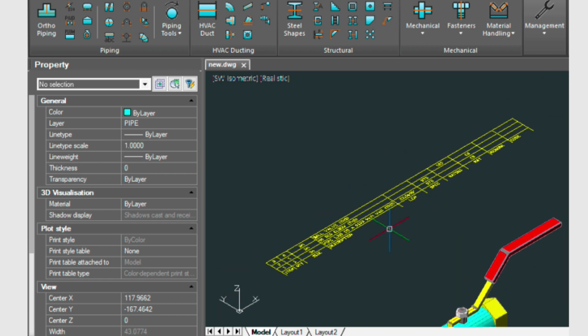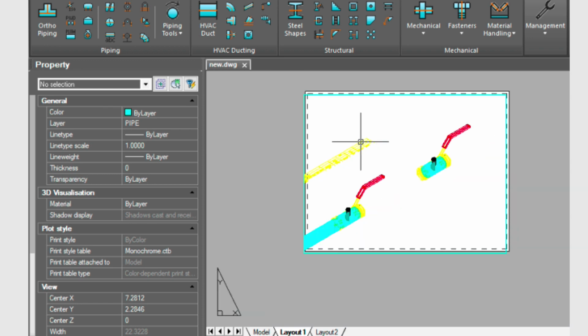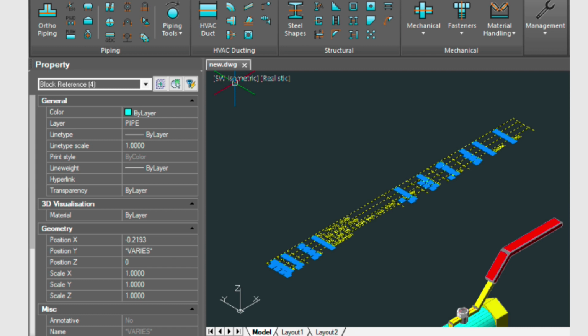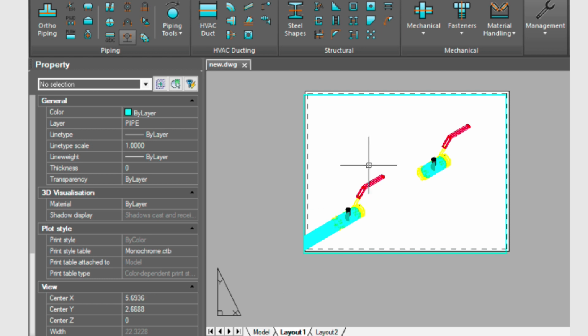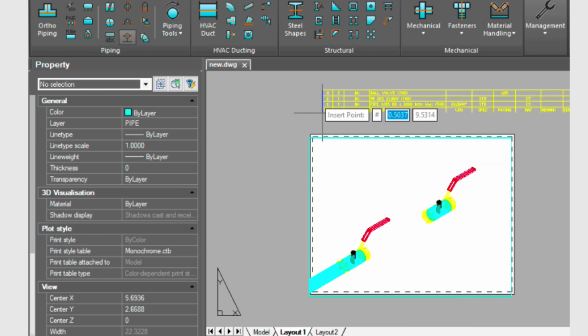Now, to get this schedule into paper, cutting this and then pasting it into paper space. If you want to hang in there, I'll show you how to do that right now. So we can just cut it, go back in and make sure paper space is activated, and then just paste it in here.